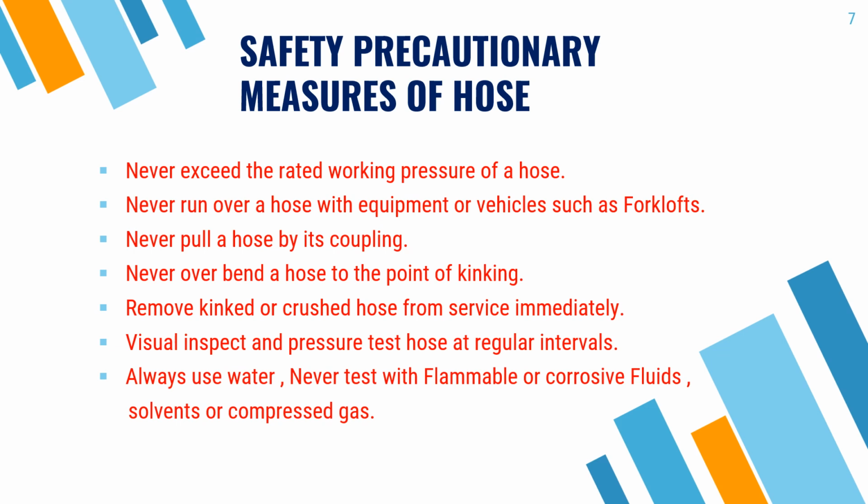And remember that whenever the concerned crew is doing the pressure test of the hose, they should never use any kind of chemical for that activity. They have to use only water. Always use water. Never test with flammable or corrosive fluids, solvents, or compressed gas.